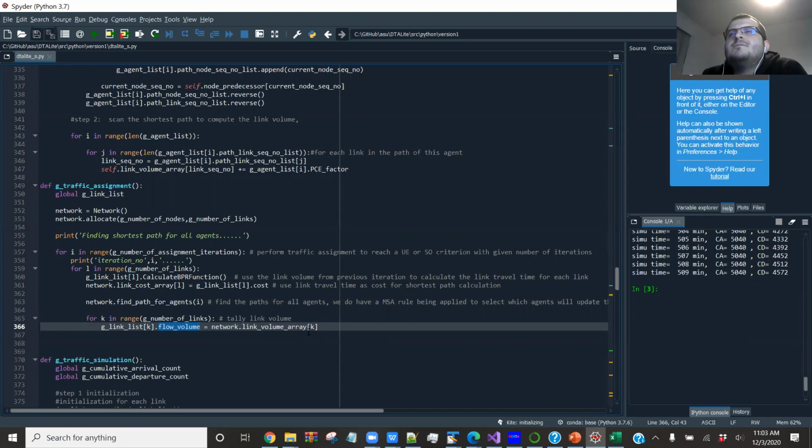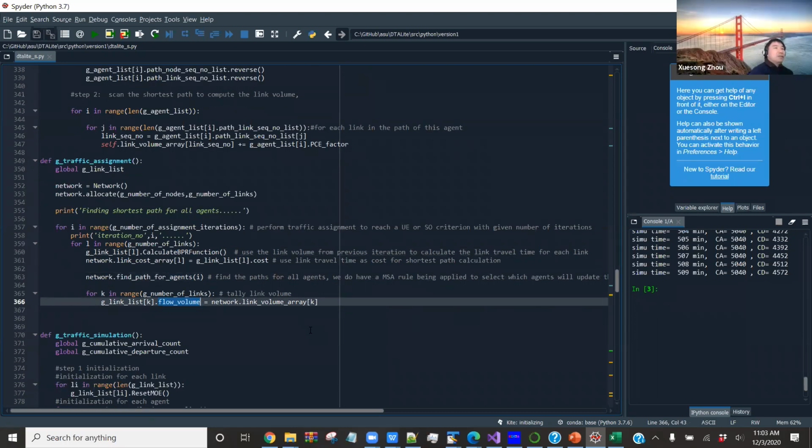Yes, got it. A common misunderstanding will be that all the agents find the shortest path every iteration, and then you can see this becomes a game process. All the agents are re-updating, and then they just do this bang-bang control. They get this shortest path congested, and then they go to the alternative path, and then they go to the shortest path again. That's why this whole process essentially is a nonlinear optimization. We need to understand the corresponding user equilibrium, system optimal, and the step size. Otherwise, it's just a one-shot simulation.